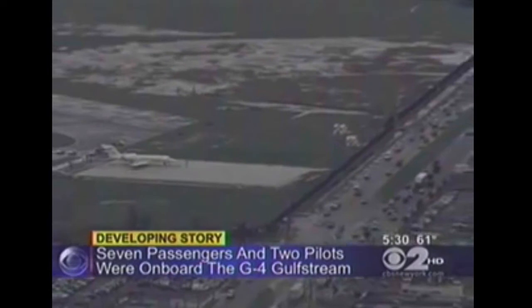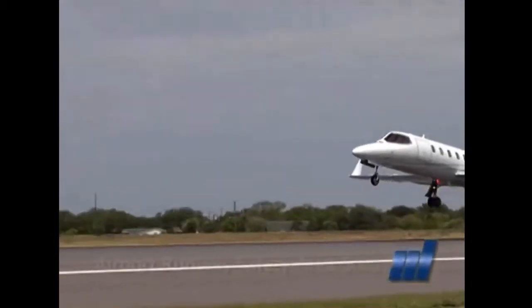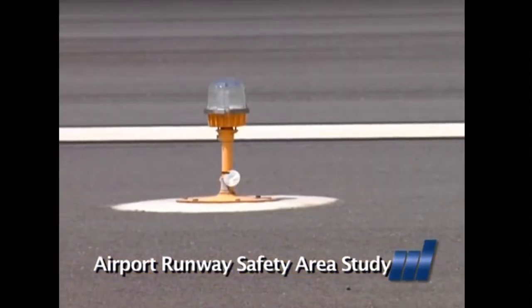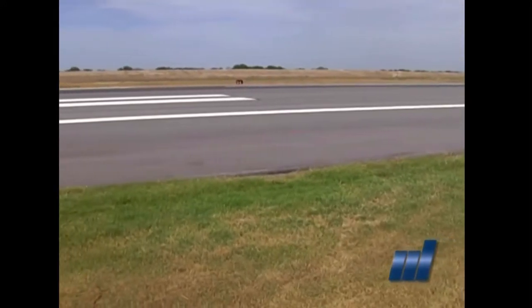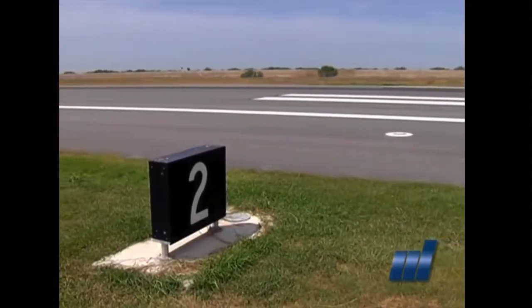With the basic concepts in hand, let's listen to an interview with Phil Brown, Director of Aviation for McAllen International Airport, to see just how much impact the Runway Safety Area program is having in the decision-making process at airports across the country. McAllen Airport officials have looked at as many as 20 alternatives to meet new runway standards required by the Federal Aviation Administration. It involves having a designated runway safety area at the beginning and end of the runway to accommodate planes that undershoot or overshoot the runway.